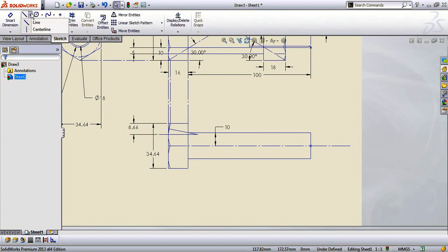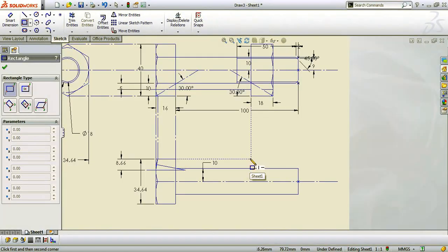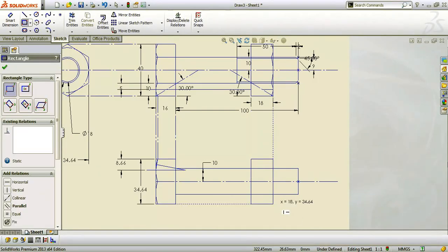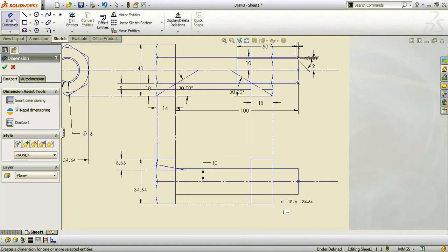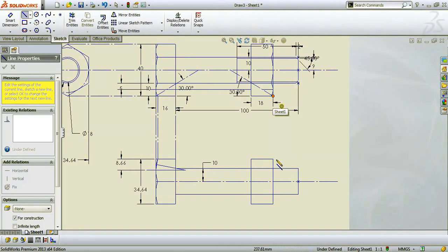Now there's one more part, that is we have to draw the bolt portion, the inner portion. To draw that, I'll take a corner rectangle. You take both the references. You don't have to give the dimension again, as we'll have a reference. The same way as I've drawn it for the nut portion, I'll take the reference line from here.